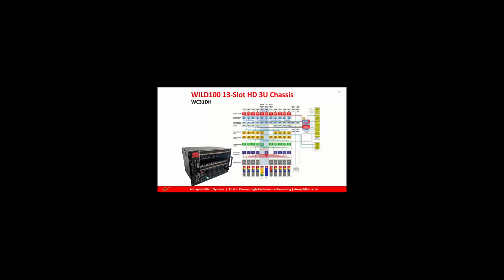And then our other slot, slot 6, connects up the expansion plane. So you can either plug an Ethernet switch into that slot and have 100 gig Ethernet connectivity, or you can plug in a PCIe LVDS switch into that slot. So if you have GPUs, x86s, you can connect using PCI Express to those slots, or you can use LVDS.